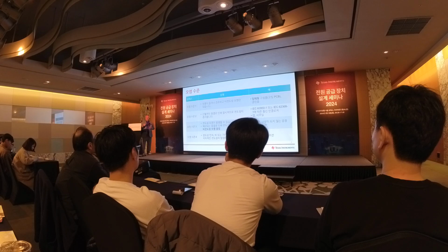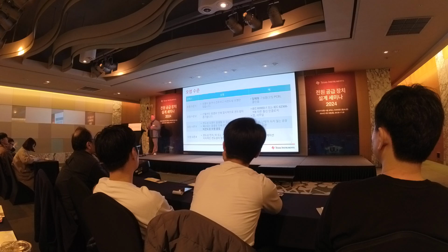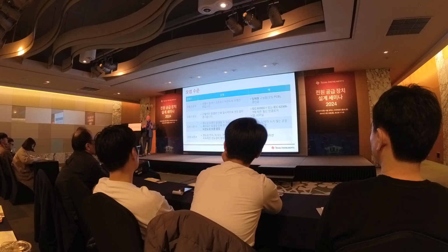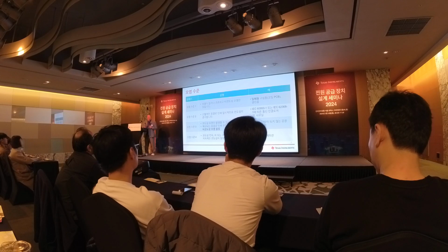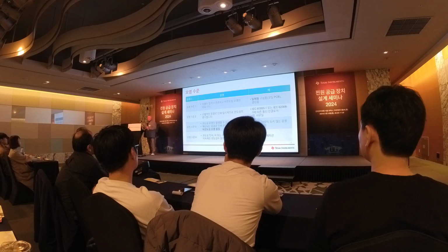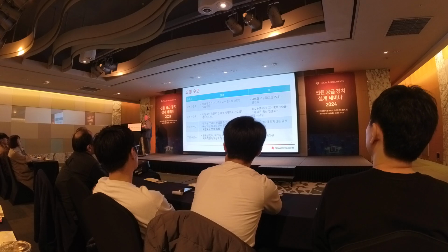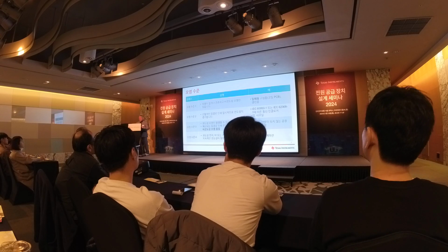So this is an industrial setting. This is an unheated factory. This could be farming equipment or other rooms in which the condensation or temperature is not controlled. And then finally we have pollution degree 4. And pollution degree 4 is outdoor applications. So this is going to be the most harsh environment.